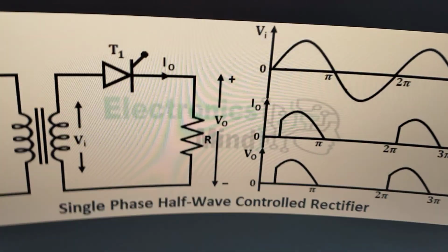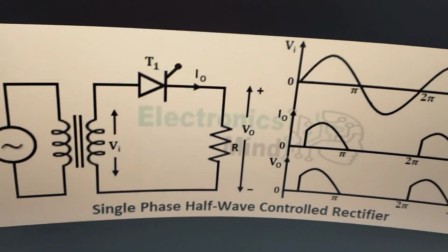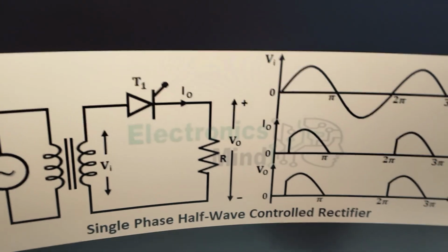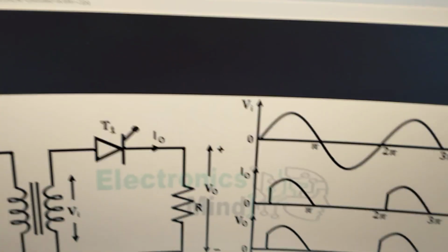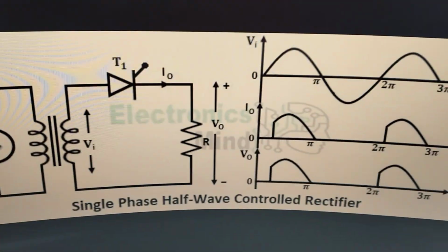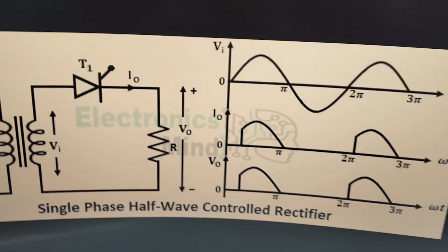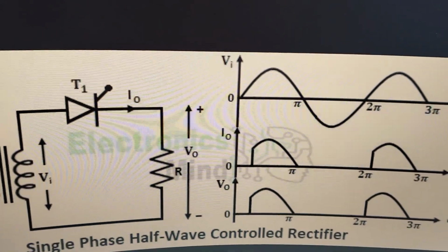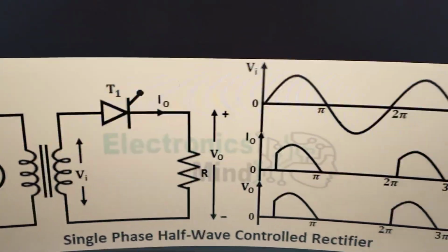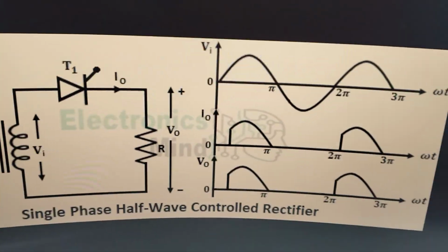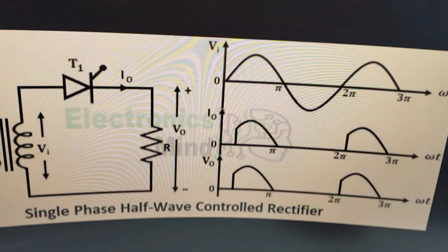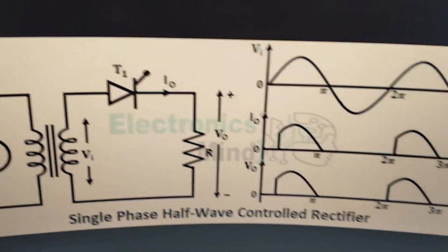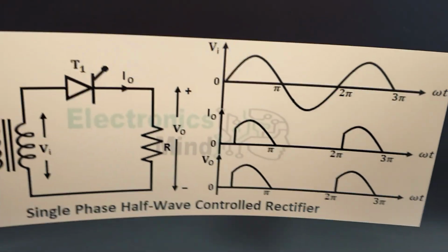But the thing with the diode is, as I said, it's an uncontrolled device. You can't really vary the voltage how much you want of this cycle. Normally, we rectify that with a filter capacitor in a standard power supply circuit, and then maybe put a linear regulator like the LM338. There are many out there. Or if you are feeling different, these days they do a lot of switching circuits, because power electronics is there. So a buck converter, probably that's what you would see today. But this is another way.